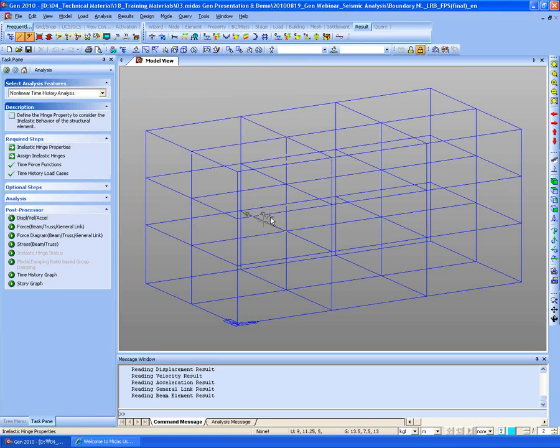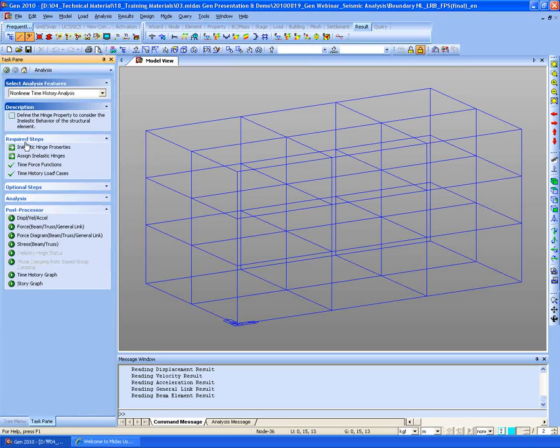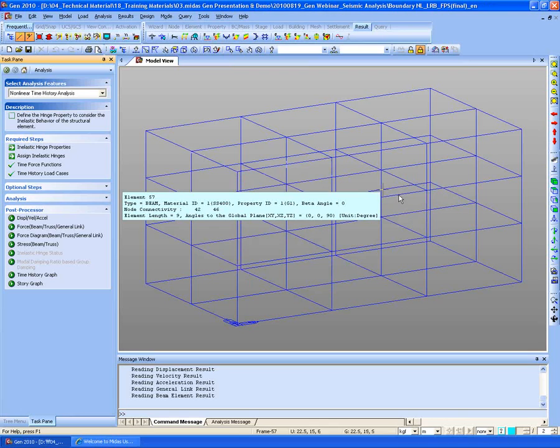When you check the model, we checked the geometric nonlinear analysis, which means the structure will be considered as linear. So we didn't assign any hinge. And we only consider the nonlinearity in the isolator, that is the geometric nonlinear. And the other one is inelastic nonlinear time history, that is assigning the hinge to the element, assigning inelastic hinges, and checking the hinge formed during the time, that is the inelastic time history analysis.